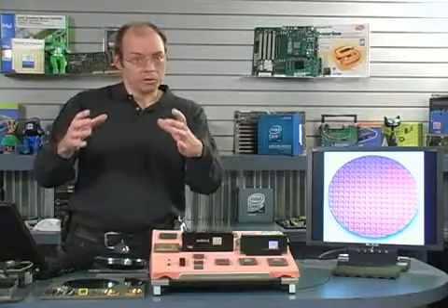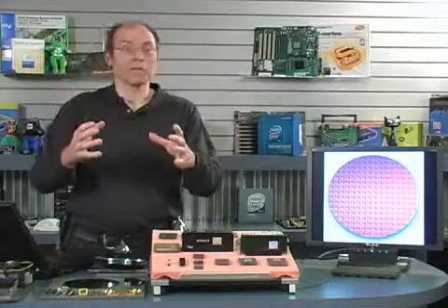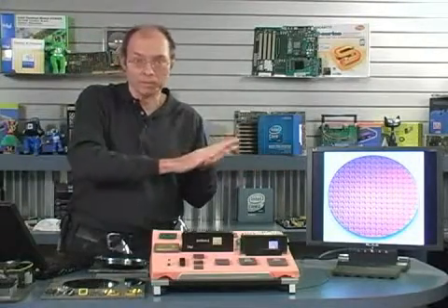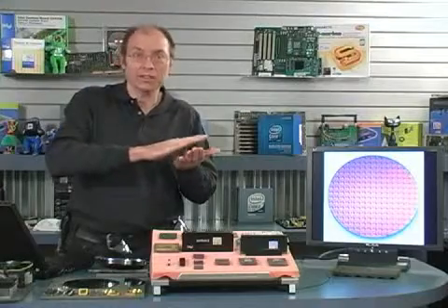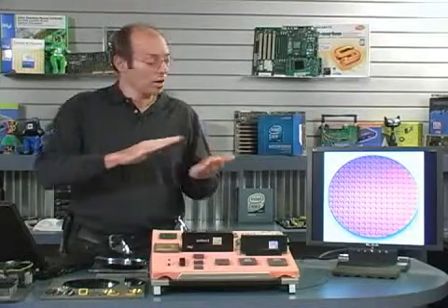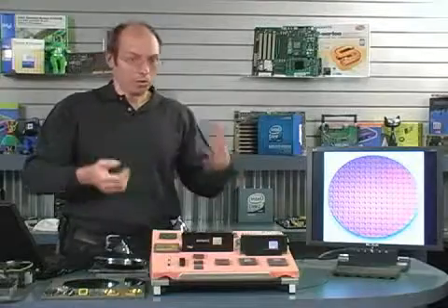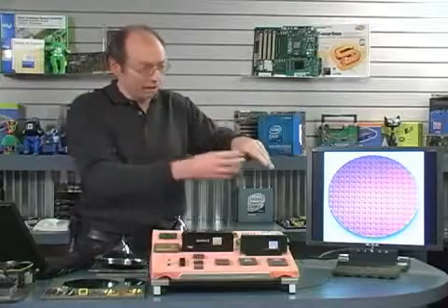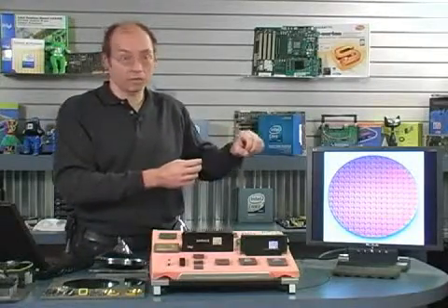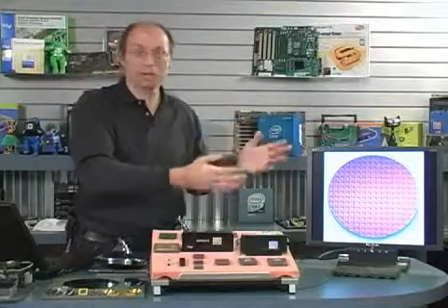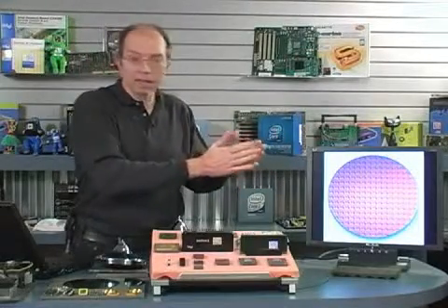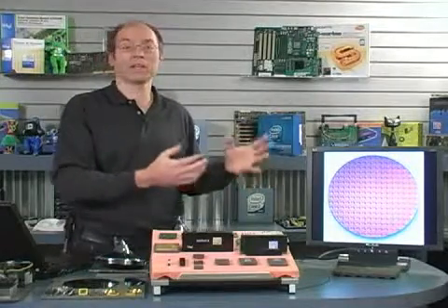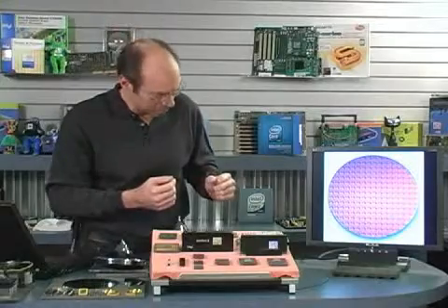One mask was used to produce this, or I should say one collection of masks, because each of these die is not just one image that's put on this wafer. It's a stacked series of images, usually 20 or more layers. Through the photolithographic process, material is coated onto the wafer, then it is etched with the ultraviolet laser, then portions are washed off, and we literally have a cake building process, layer upon layer upon layer, until this very complicated series of circuits is assembled.